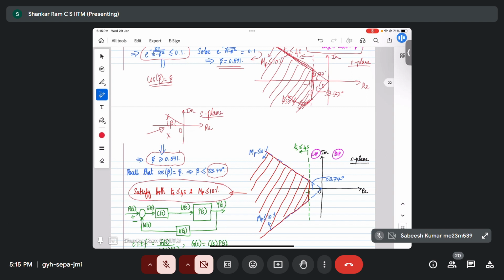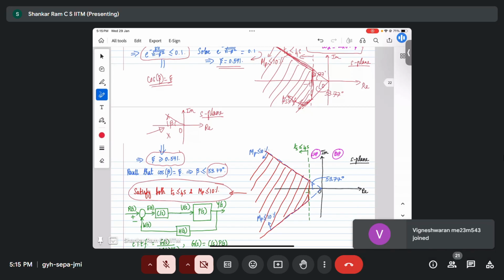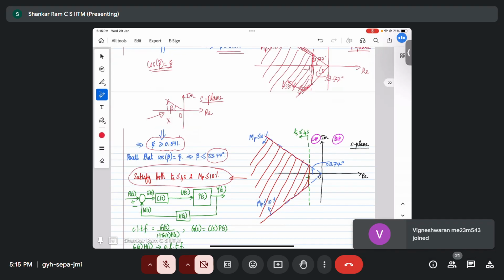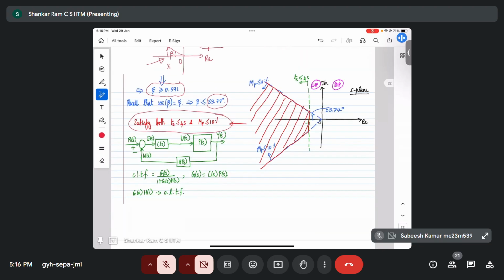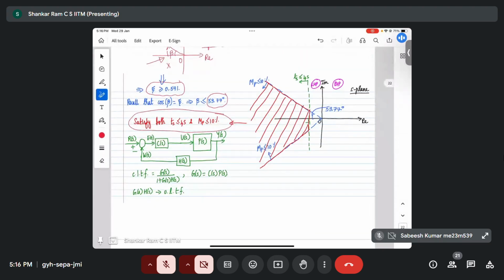So this is how we convert it. Now, how do we go forward? We go forward now to control design. We are just recollecting what we already studied. We are looking at the negative feedback closed loop system. We drew this block diagram representation this week, and then calculated the closed loop transfer function as G(s) divided by 1 plus G(s)H(s).